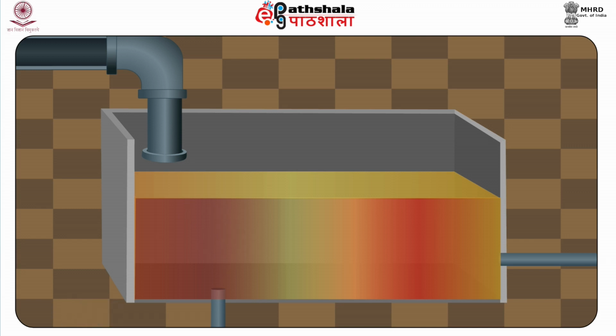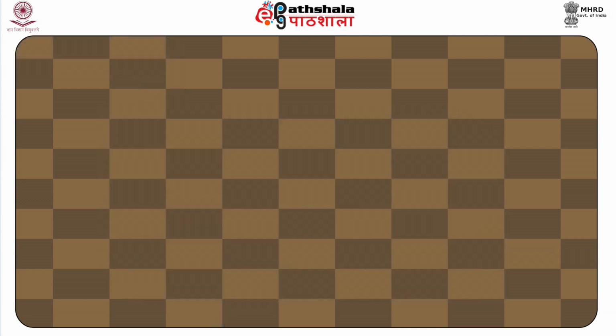When the glass is sufficiently refined and homogenized by removing the bubbles and impurities, the temperature of the molten glass is reduced to 1100 degrees Celsius as it passes down the furnace towards the forming stages. This process is important for producing high quality glass and can last up to 50 hours. Glass does not have any certain melting or freezing point, but it changes progressively from a viscous liquid to a rigid solid as its viscosity increases on cooling.